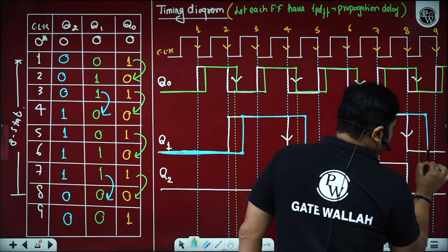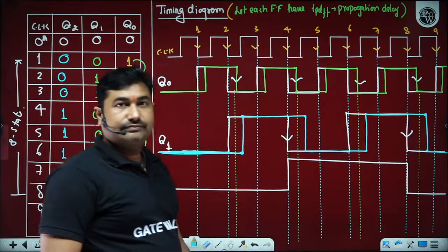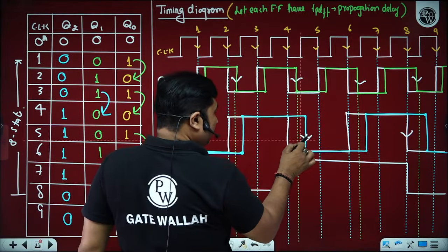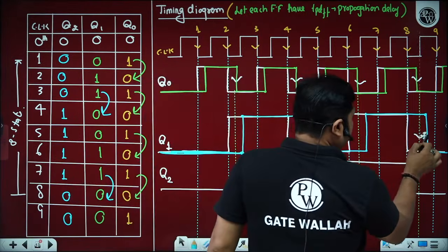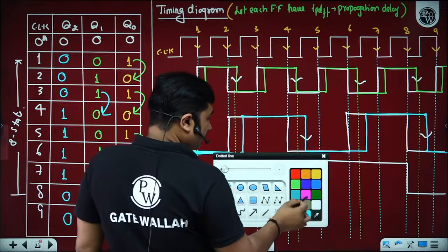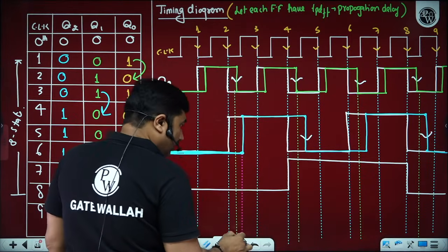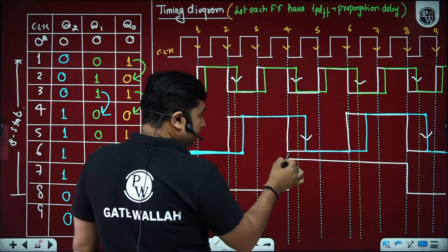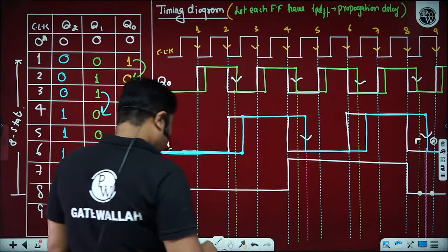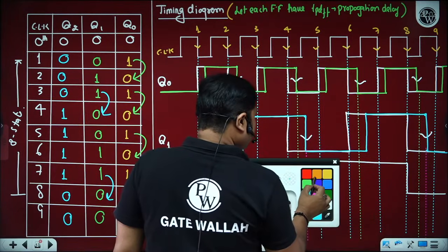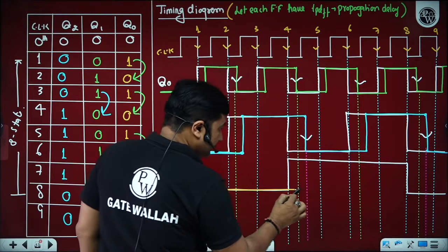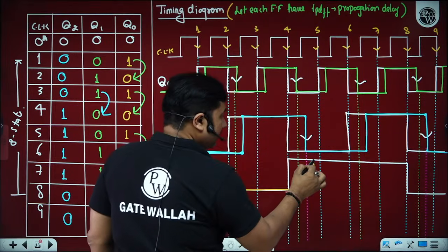How many of you able to understand, beta ji? Great, sir. So now the clock onto flip-flop 2 would appear when Q1 changes from 1 to 0. So instead of the clock appearing here, the clock is now actually appearing at the pink positions. So if the clock appears at the pink positions, instead of having this white line of Q2 as output, we will get this as output.